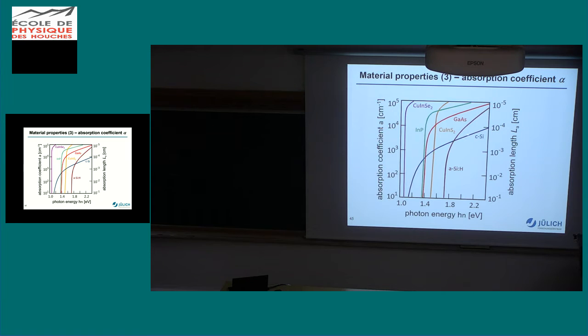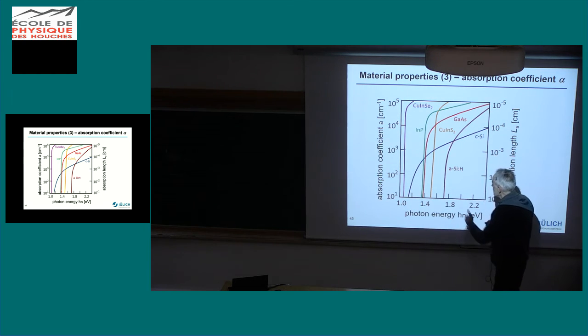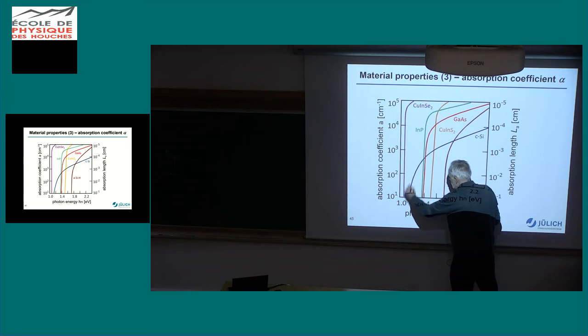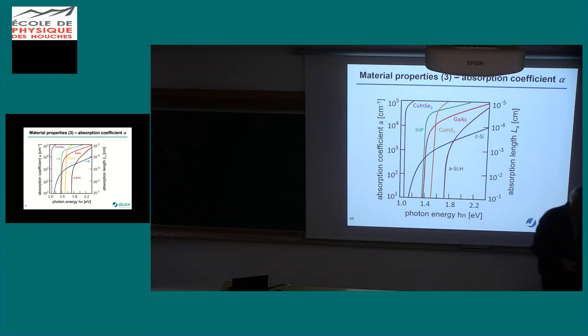In contrast, for crystalline silicon, if you just have a thickness of 1 micrometer, you see you lose a lot. You lose almost everything in that range in between. So your open circuit voltage, your recombination is made by that energy. J naught would be high because that energy is relatively low. JSC would be very small because this would somehow correspond to much higher energy.